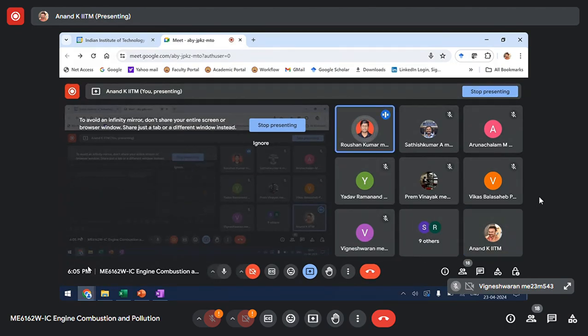So that means the total NOx emission will be almost similar for SI and CI, right, sir? Yes, this is what I said in the beginning also. NOx is comparable for SI and CI. Right, sir. Still, it is being told that CI engine has more NOx compared to SI. Why is it so? NOx control is problematic in CI compared to SI.